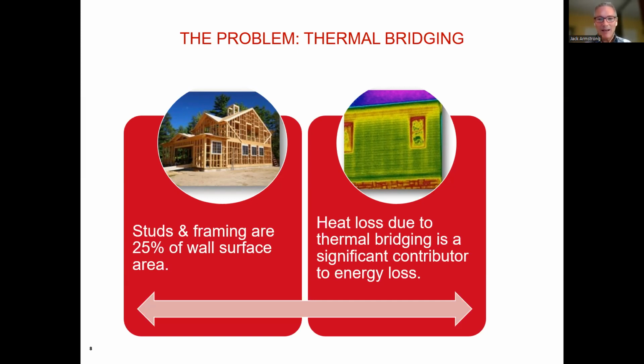So as we talked about in the larger previous class, stud framing actually creates a problem. Every time you have a stud wall in your cavity light frame construction, that's a place where there's no room for insulation. And if you add up nominally every 16 inches on center, or in advanced framing every 24 inches on center, where you have a stud, that's a place you don't have space for insulation in the wall.